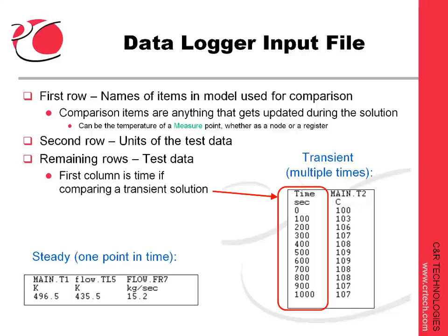SINDA will automatically stop at each such point, independent of the time step and output interval considerations, in order to perform a comparison at that point. Remember that you may use several data loggers in each model, each one pointing to a unique file, and each file itself might have unique time points.